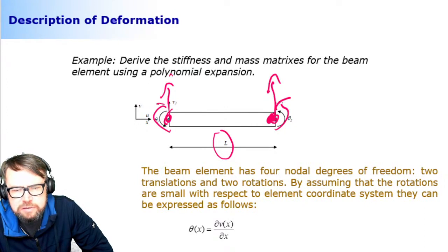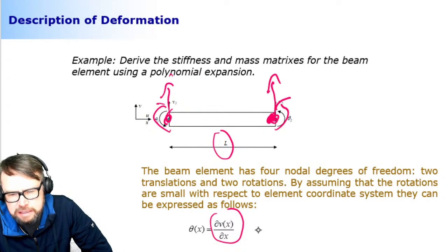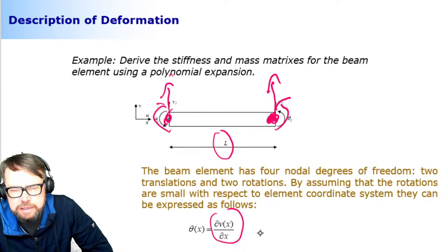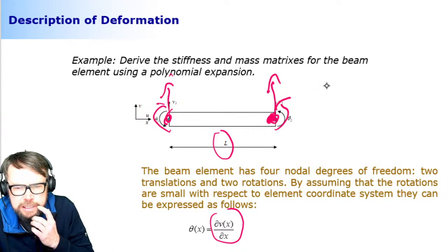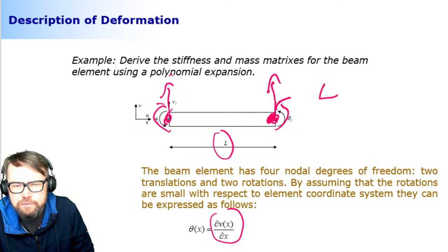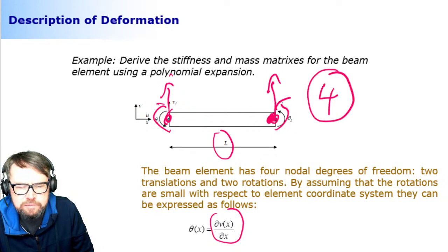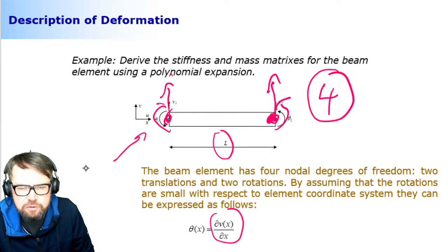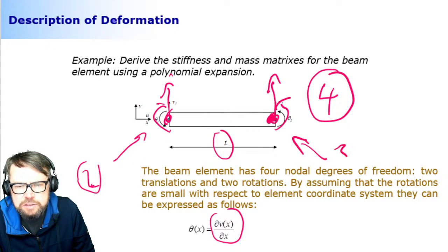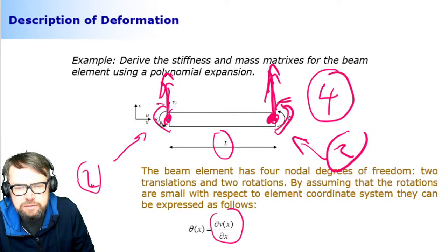And then it is known that the displacement in the y direction and rotation are combined through a partial derivative operation. So that's going to be my element here. So a total of 4 degrees of freedom, because 2 degrees of freedom are associated to the first node, 2 degrees of freedom are associated to the second node. And again, there's displacement in the transverse direction and rotation.